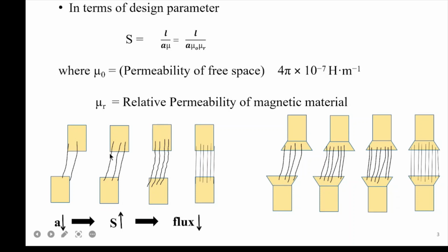In the second diagram, the rotor is going to align with the stator. So most of the portion is aligned, and flux lines will be more compared to this. And again, in the third and fourth, it is exactly aligned, so flux lines will be more. But depending upon the width of the pole taken in the stator and rotor, only that portion is linked, and only that portion allows the flux lines.